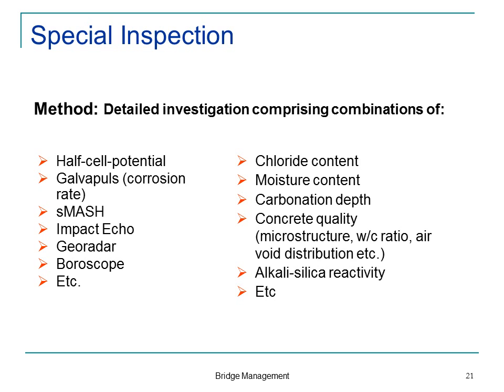We focus a lot on the corrosion. The corrosion is an electrochemical process, which is why we typically measure the potential of the reinforcement, because that gives us an indication of the risk of corrosion. It also gives us an indication of where in this structure it might go wrong first.